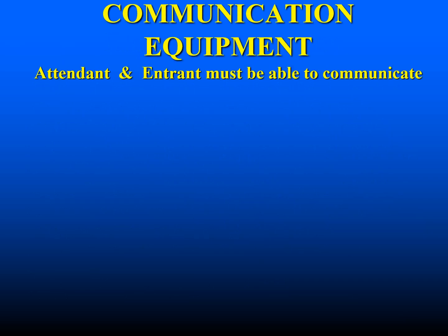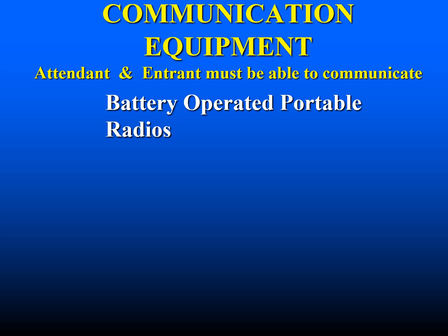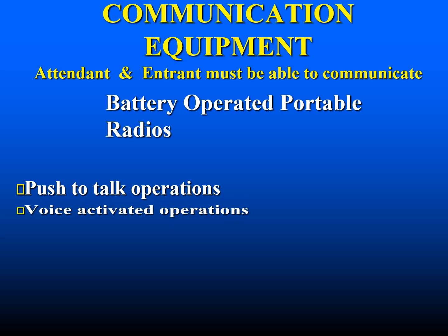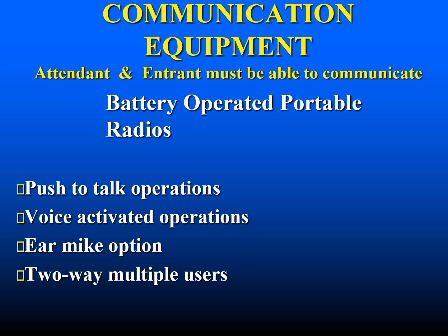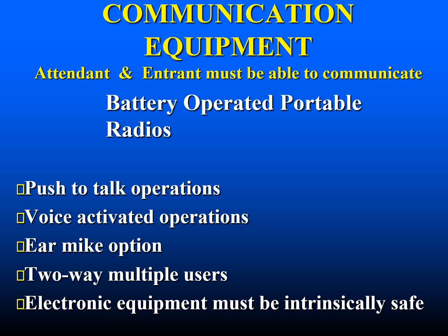Now let's talk about communication equipment. The attendant and entrant must be able to communicate. The equipment must be battery-operated portable radios, capable of push-to-talk operations, or it can be voice-activated operations. People can use an ear mic as an option, and you can have 2-way multiple users. Most importantly, the electronic equipment used must be intrinsically safe.